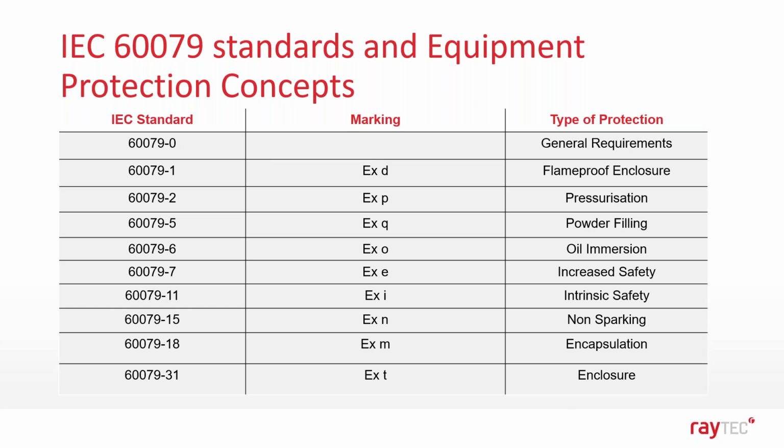Now the top one there, 60079-0, these are the general requirements electrical products must comply with. Products will then use a protection concept or combination of concepts outlined in the other series of standards to provide an overall compliant product. So for instance, 60079-1 provides the requirements for flameproof enclosures.